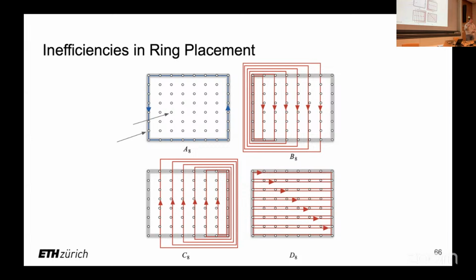And I believe there's actually one area where you can improve this efficiency, and that's exactly the 4th group. If you remember, the first 3 groups already assured connectivity between all cores, and the 4th one was just to improve the average hop count. However, if you think about it, this is extremely regular, especially if you add more of these. They always build the same pattern and connect the same cores. Even in your smaller designs, they have exactly the same pattern. Obviously, you rotate them 90 degrees, but after you've rotated them 180 degrees, you're back at the same design.